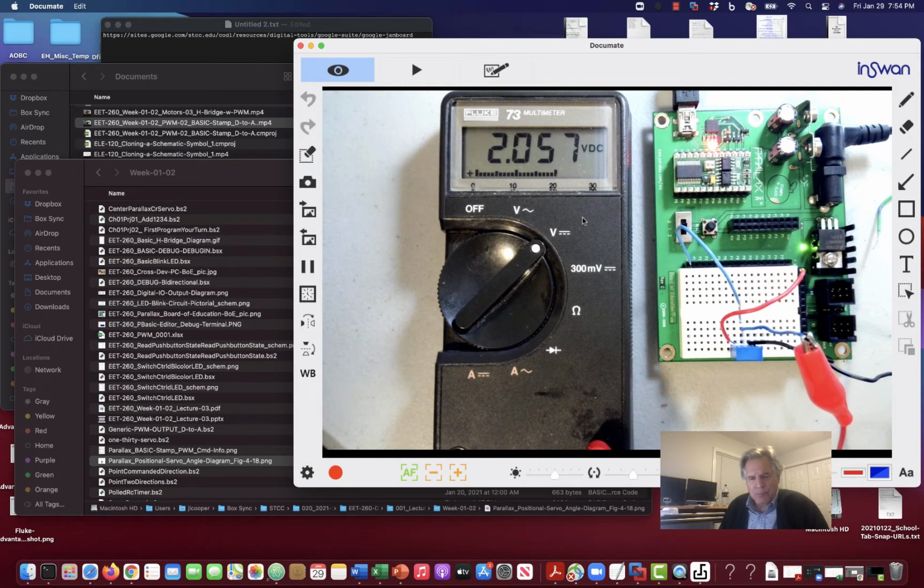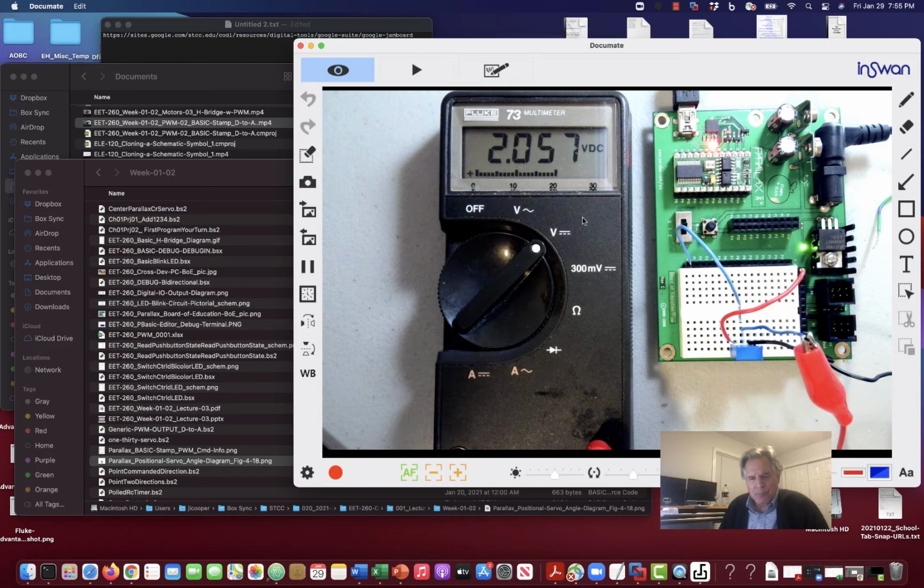Transistor logic, or TTL, is actually a bipolar solid state technology. It uses bipolar junction transistors. MOS, or CMOS, specifically CMOS logic, like the famous 4000 series, or the variants that copy the 7400 TTL, like 74C, 74HC, 74HCT, 74LVC. It's just an alphabet soup of logic families.